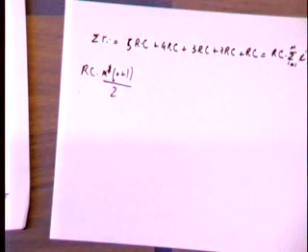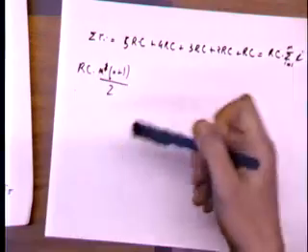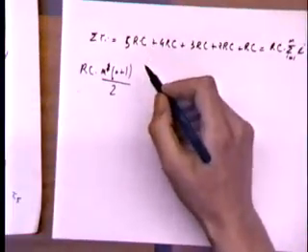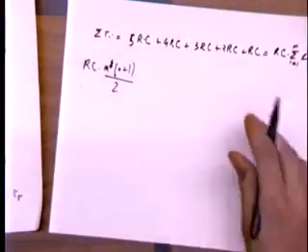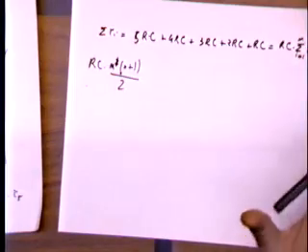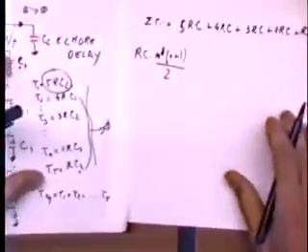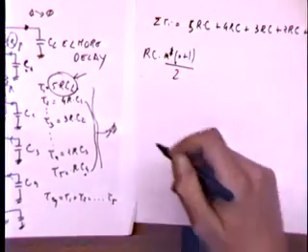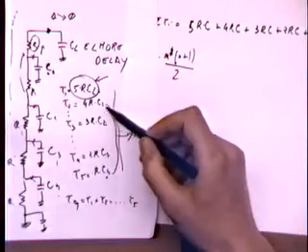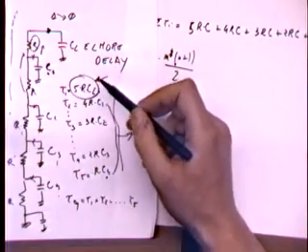And this indeed is what you observe in simulation, okay? It's a little smoothed out by the fact that usually CL is bigger than all these Ci's. But indeed, what you can observe is that if all the Ci's were zeros, the only term that would remain would be the term with the CL, right? So you will get linear delay in the number of inputs. If all these other C's are 0, then you only get this term, okay? So in other words, if you don't have parasitics of the transistors, you only get the first term, which tells you linear delay in the number of inputs.